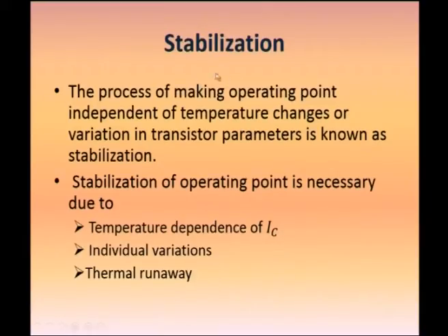What do you mean by stabilization? It is the process of making the operating point independent of temperature changes or variation in the transistor parameters. It is necessary due to the temperature dependence of IC and individual variations, that is, if you replace the transistor. There is also a condition called thermal runaway. We will see it now.